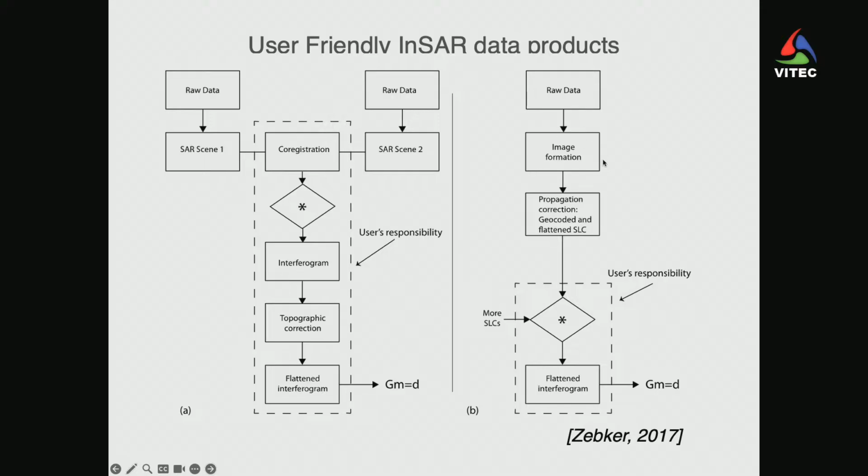And then you work through the image information directly from the raw data, so form the SLCs, and then with the image information, you already resample it to the lat-long grid right now. Because eventually you are gonna work with a geogrid. Why not, instead of everything resampled to different radar grids, just resample them to that final geogrid, right? So that's intuitive, but it just hasn't happened before this.